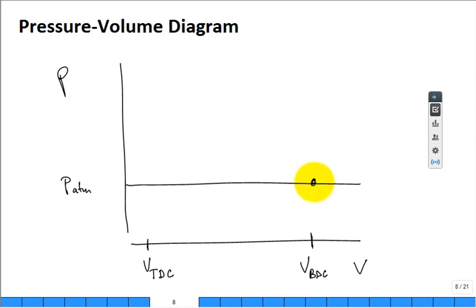So as you compress, there are no valves opened, and it leads to a rise in the pressure. Somewhere around in here, a few degrees before top dead center, it's controlled by your distributor mechanically. It used to be; now it's all electronically controlled. It senses when it should be firing that spark plug. Often at idle, maybe it's set at 12 degrees before top dead center.